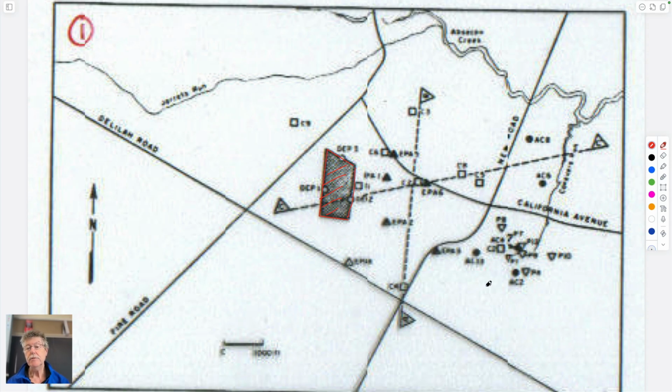So you take some samples. How do you, if you're standing in a field, figure out what's going on? You don't know the stratigraphy, you don't know the direction of groundwater flow, you don't know anything about the site, you don't know the size of the plume. So you drill some holes to investigate. You take water samples, perhaps you take samples from places where the plume isn't, and then you try and reconstruct what's going on. So one way to reconstruct what's going on is actually quite similar to one of your assignments.